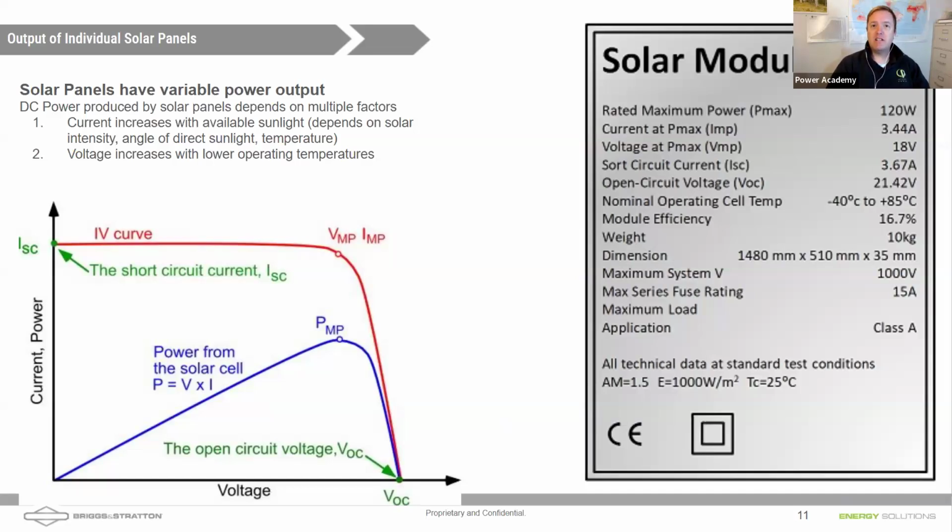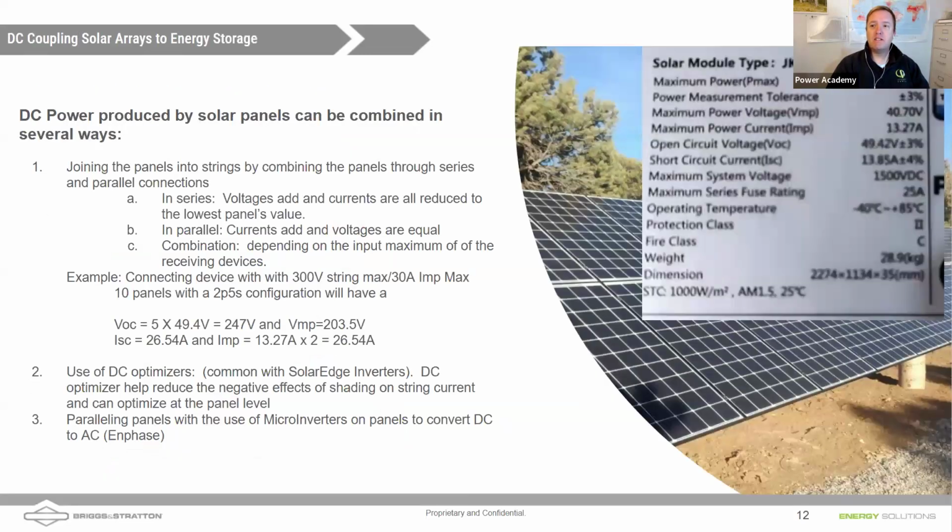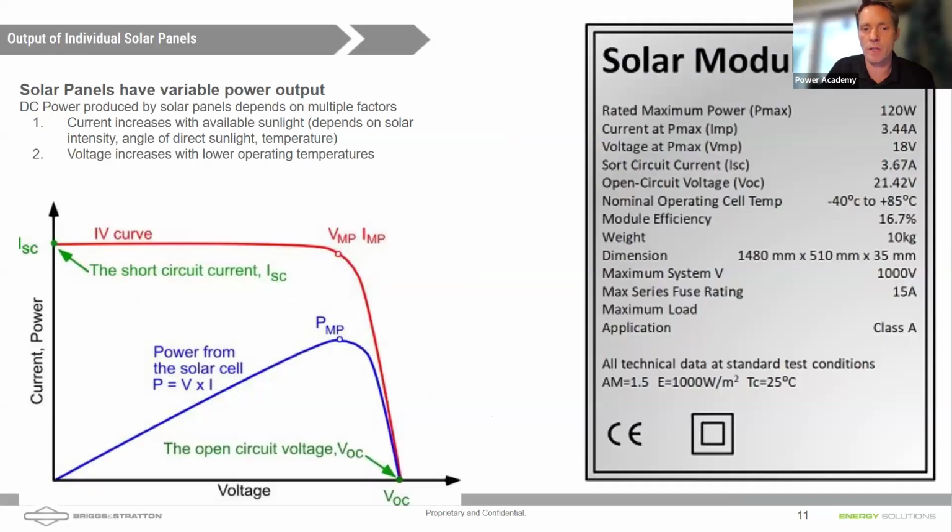And then on the next slide, Nathan, this panel has a much higher voltage, which is more acceptable when we're using a charge controller with maximum power point, where it can adjust that point to meet what we need to charge the batteries. Yes, good point. And Daniel, we just talked a little bit about what can influence the voltage of a panel. Certainly the amount of current that comes off of a panel changes the voltage. That's what this slide is showing, right? But you also mentioned temperature.